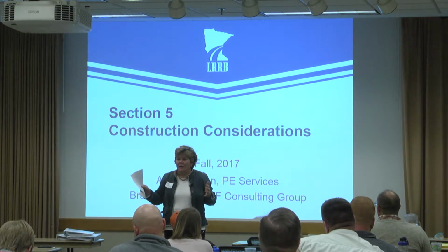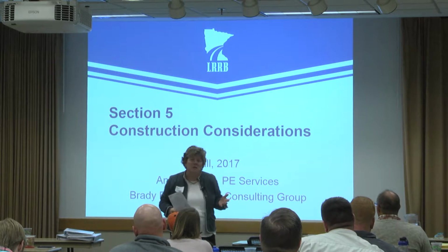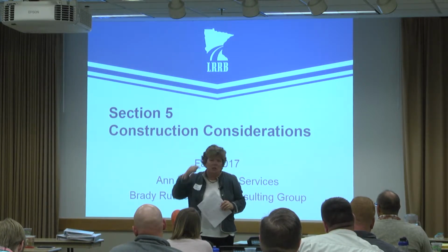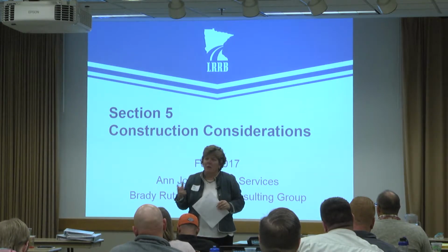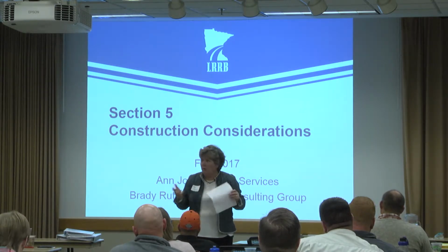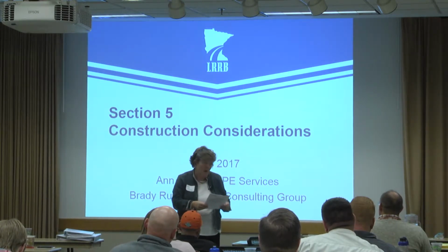Somebody said it takes 2 seconds to take a shot. Who said that? It's really true. It takes 2 seconds once you have a rod up. You don't even need to shoot to a benchmark. You're just looking at change in elevation. So I guess you do get a feel when you're out on a job site as to what kind of contractor you're working with and if they're doing good work. But for me, doing a spot check is always worth the time.